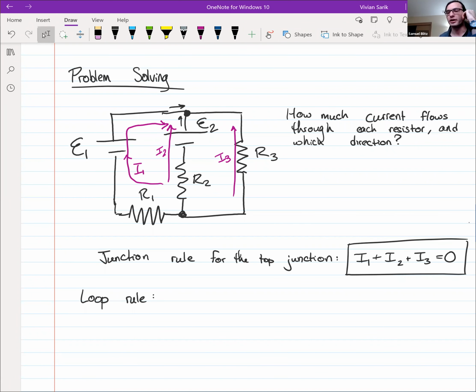current is almost a vector quantity. Current isn't quite a vector quantity, it's really just positive or negative, but we say that current is positive opposite the direction of electron flow. So if you find that the current is negative, that's in the direction of electron flow, but we define current to be opposite that. That's why you would have to change the direction in your model of the current flow. The idea is that current should just be a number. It shouldn't be a vector. If current is negative, it just means it's flowing in the opposite direction from the direction that you thought it was flowing.